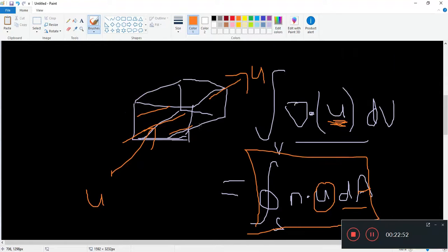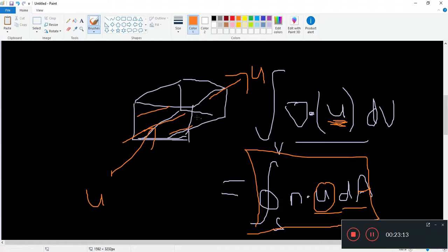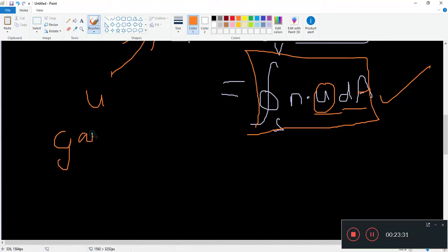So that's a pretty simple thing, right? Both of these are talking about the same physical thing: the net inflow or outflow, net outflow of some quantity like velocity. So to integrate the divergence across this volume, you need to do a surface integral, meaning you have to check the inflow and outflow at each of the surfaces of this cube or hexahedral. This is called Gauss Theorem. This is a very, very brief run through. I hope you are familiar with it.